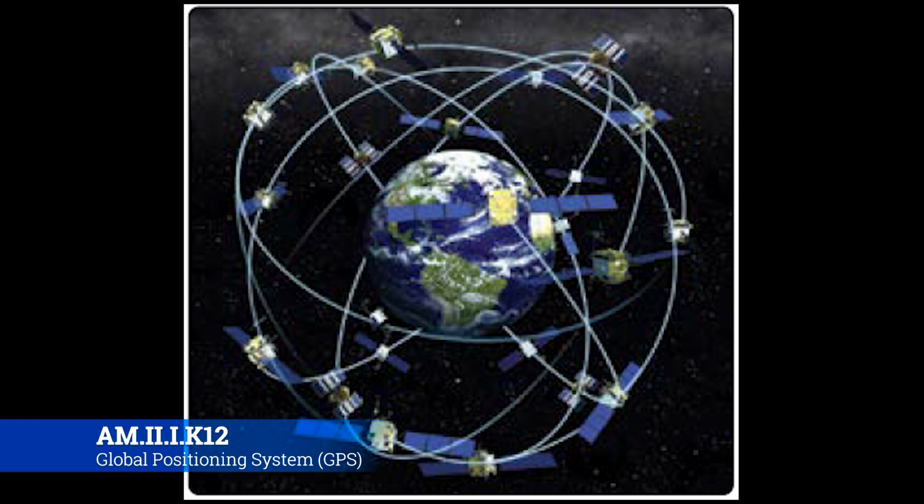You don't have that problem with GPS because there are so many satellites up there, and what they're effectively doing is triangulating where the airplane is relative to those three satellites, just like those two guys did with Sputnik. We know the time it takes for a GPS signal to leave the satellite and come to the airplane, and we know how to receive those signals and then time them. On those signals, there will be a unique satellite identifier and a synchronized time whenever the signal left, and that's what it transmits.